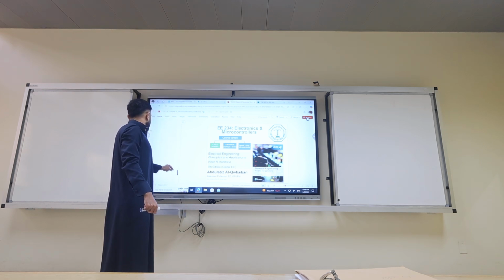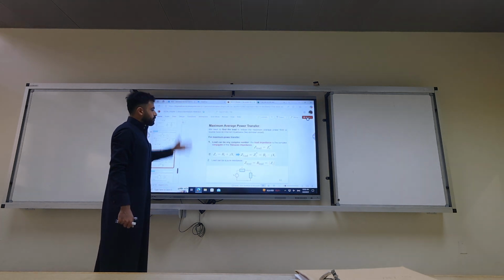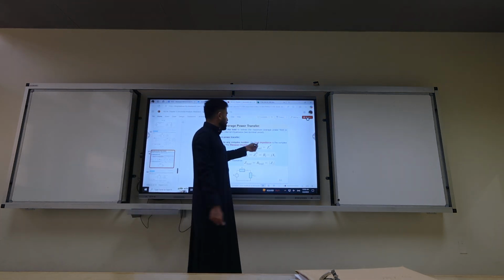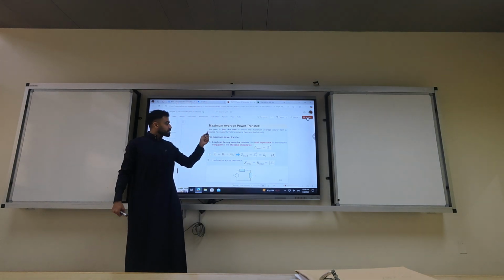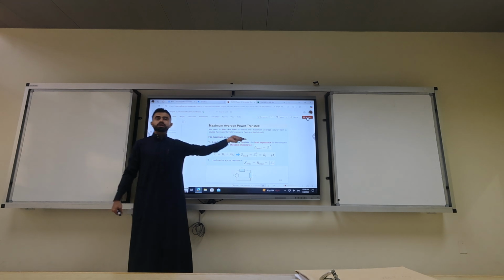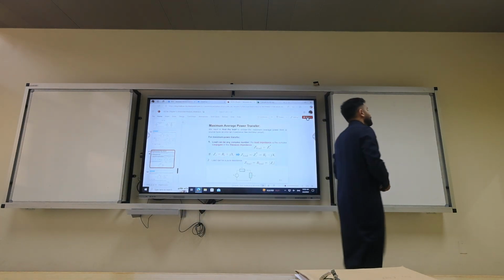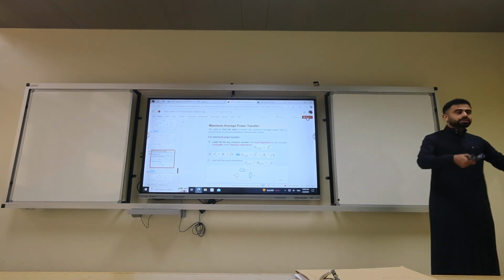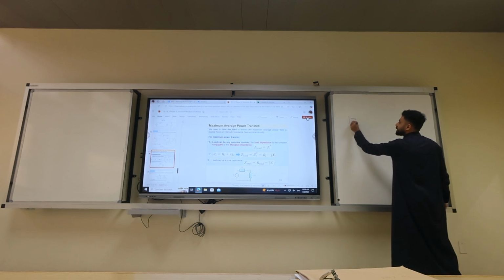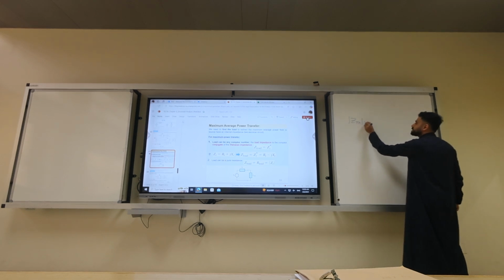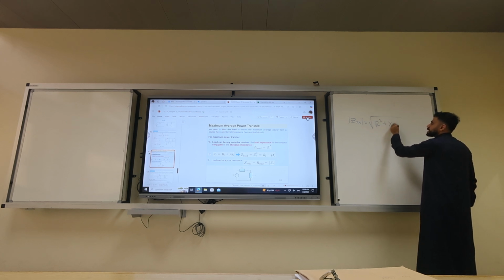Today we will recall some of the problems from the previous lecture. What did we mention? There are two maximum power impedances. One is complex, which is the conjugate of Z Thévenin. One is real: if you're allowed only to connect resistors, it has to have a value of the absolute value of Z Thévenin. How to calculate it?